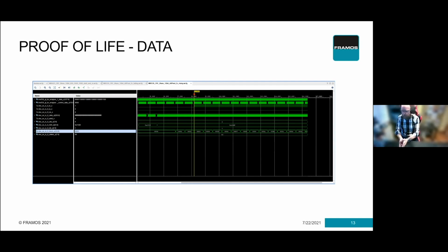I know I'm rambling on this one a little bit, but it is very worrying when you have a CM that doesn't realize that these sensors are very expensive. The guy who's doing the bill of materials and charging you out knows that, but the person on the line doesn't realize that device is actually a $1,000 device, for example. And so they can immediately just run everything through, and then they've suddenly got 100 image sensors on boards that don't work. They all need to have a different amount of solder paste on, but you can't recover that sensor, because reheating that sensor from above to melt the solder underneath to take it off makes that sensor experience a temperature range way beyond its specified temperature.